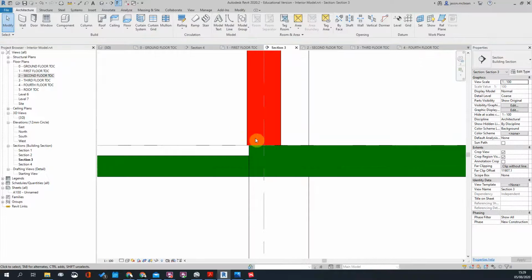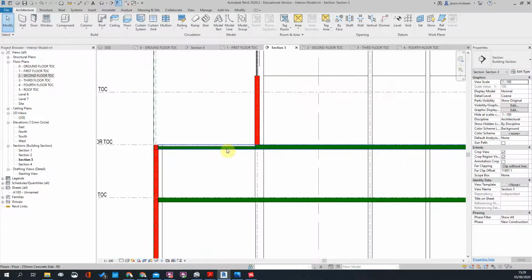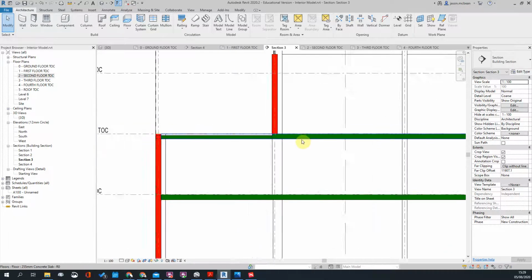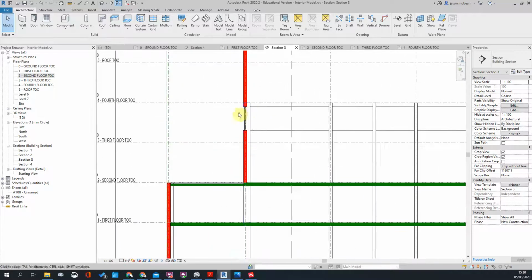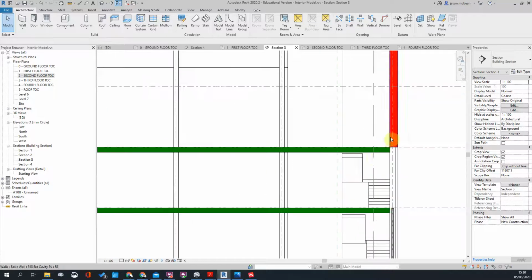It's 85 lower because you can now put a screed layer and it can fall to the external side. And they make the slabs thinner. Okay. You can use the join tool to join these slabs together in a minute. And you can see our shop fronts are starting to work. The windows in these areas are starting to work well. Okay. So that's that in a nutshell.